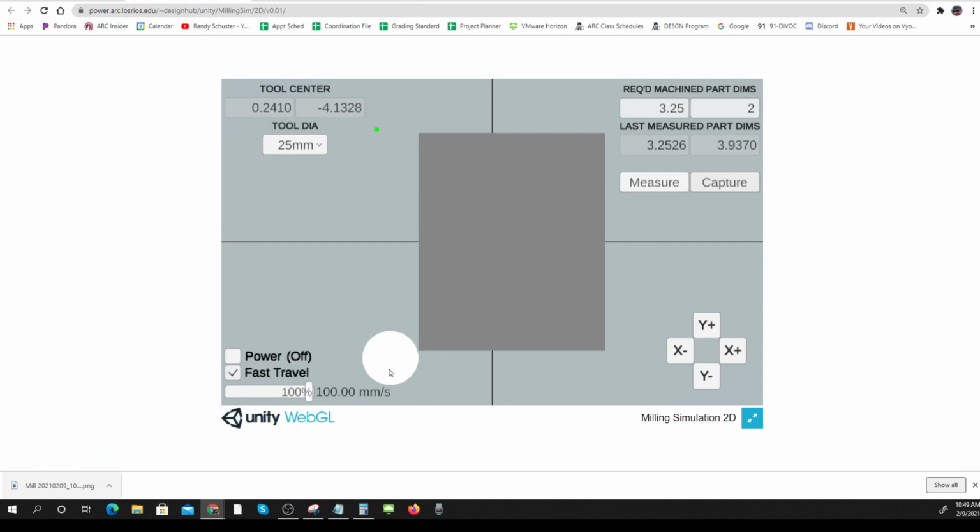This is in millimeters, so if you're calculating radii and diameter, you have to recalculate. And that happens. Often with machine tools, you only have a metric set of tool heads, of cutters. Okay? Notice that the travel is in millimeters. That's happened to me over and over and over again.